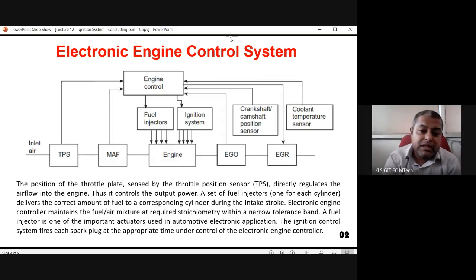Okay, so all this ignition control is happening through this part, and these may be the 4 spark plugs for 4 cylinders of the system, and they are actually initiating the combustion process. So fuel is being sprayed from the left, this side top. Air is coming here. So inside the engine a proper stoichiometric combustion mixture of air and fuel is produced, and when that is compressed, at that time exactly, proper timing and angle control of the ignition is very important.